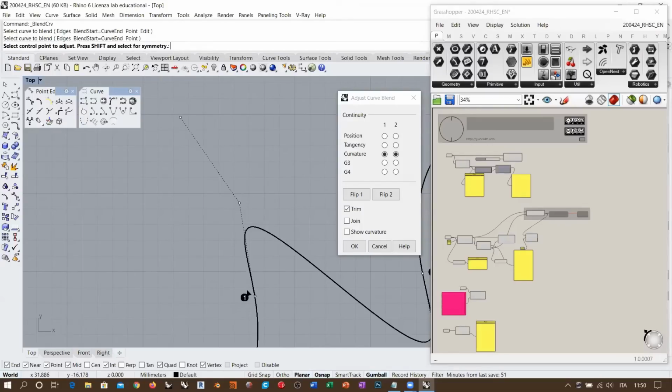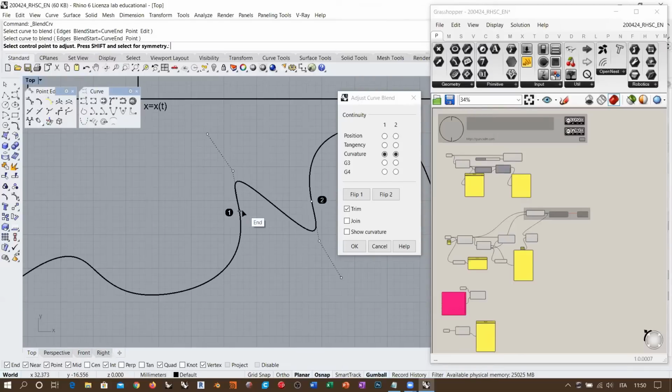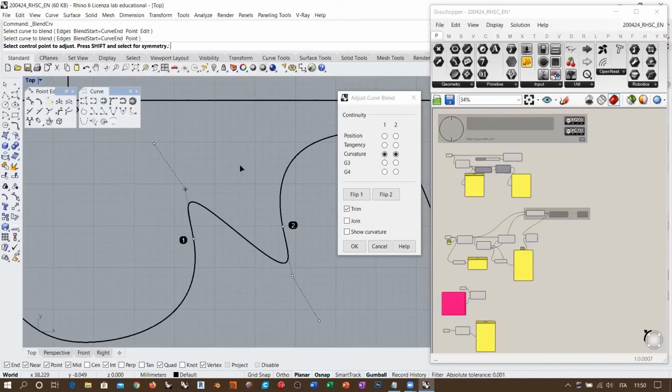They have some angle here. If they are 3 control points, they would create a degree 2 curve. The arc, being part of a circle, is a degree 2 curve. So these 3 control points here are defining exactly the control polygon for an arc. This arc represents the curvature of this first curve in the end point, okay? We are going to see this in detail later, but I'm going to just show you why it's impossible to place these 3 control points by hand.